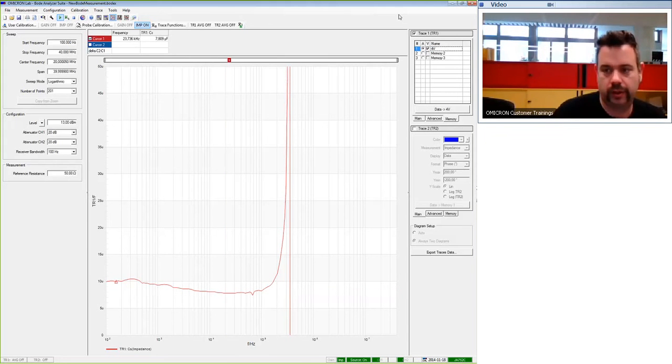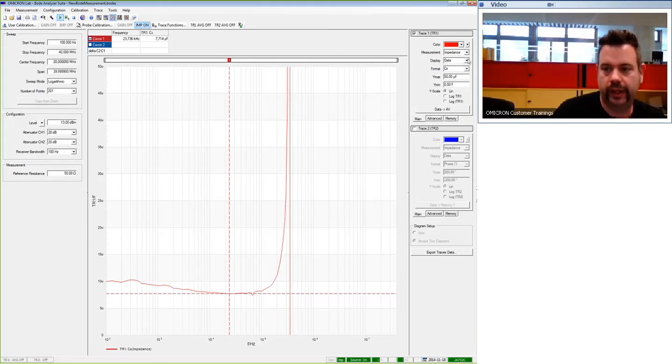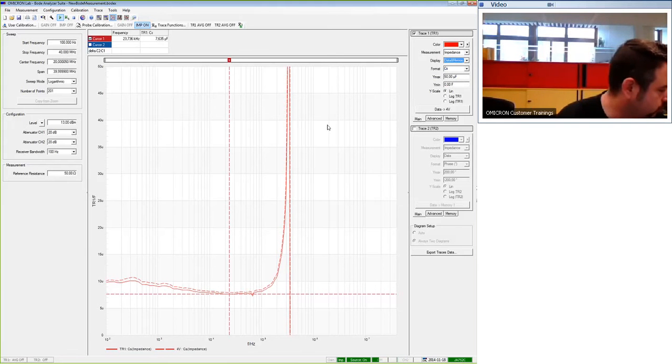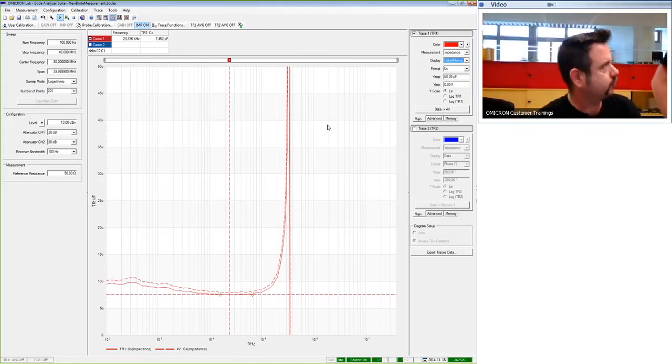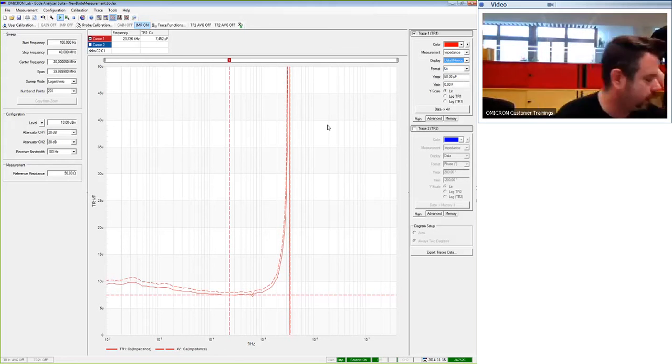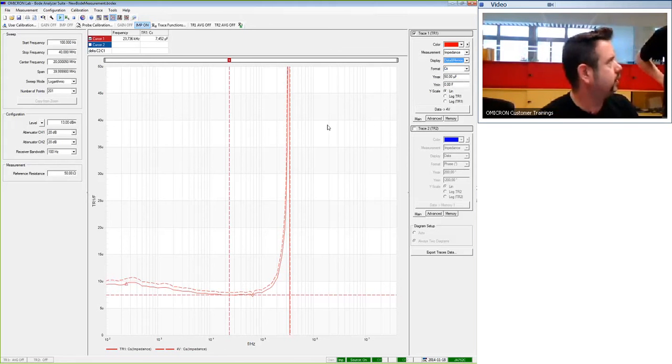And now we go back and activate data and memory. Usually you always have to wait a little bit when you apply voltage, because the capacitor needs to charge. And yes, this is also a thing to be taken into consideration. We said it's 4 volts. The DC bias injector has some loss, so to check it, you can also measure directly at the component.